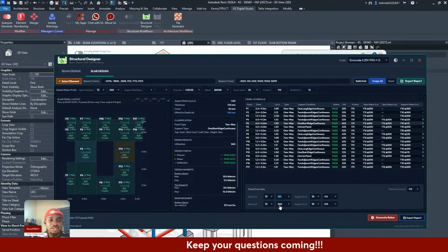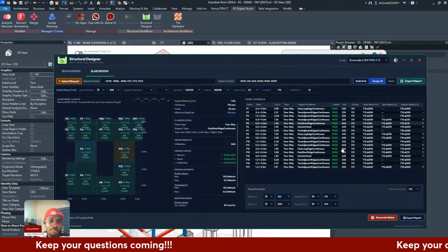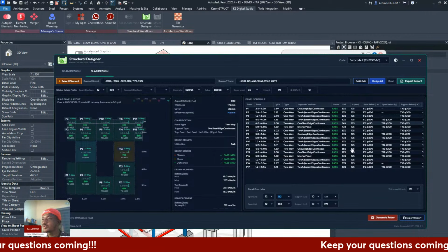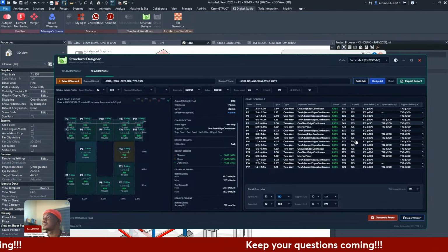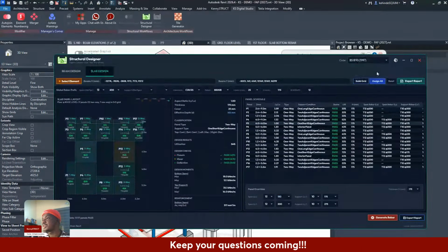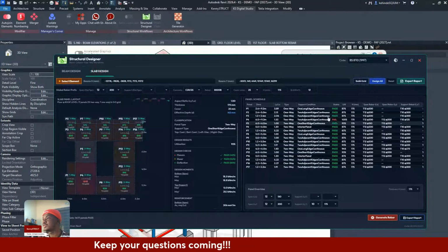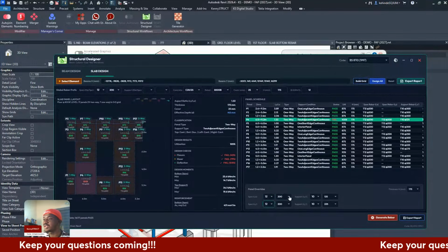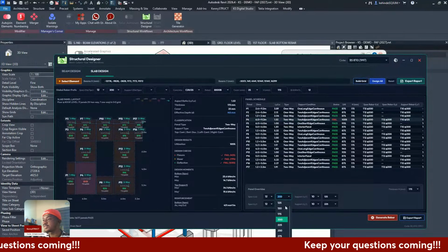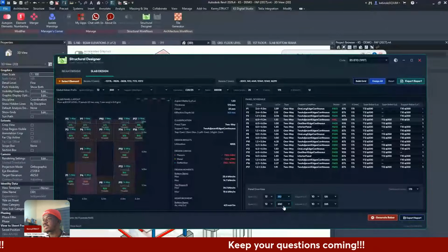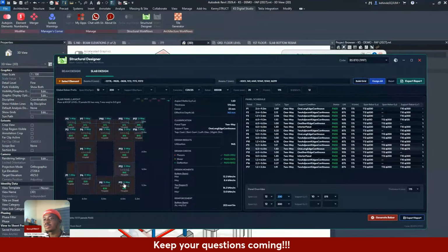This is using design codes, Eurocode and BS Code, depending on however you want to. I can see this running for you, basically BS Code. I can play around the reinforcement for this, make it work. Yeah, it's passing now, so I can say all the slabs are passing.